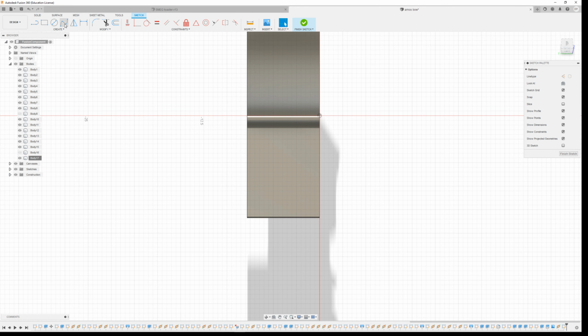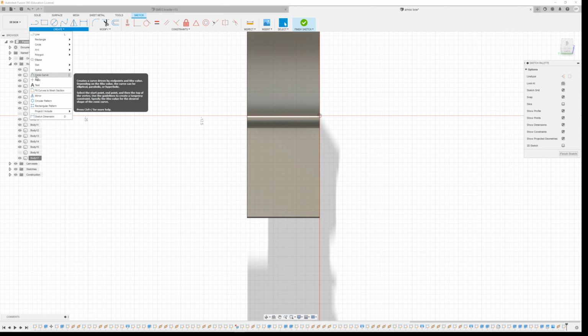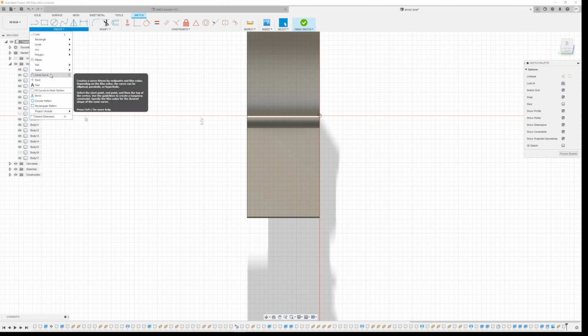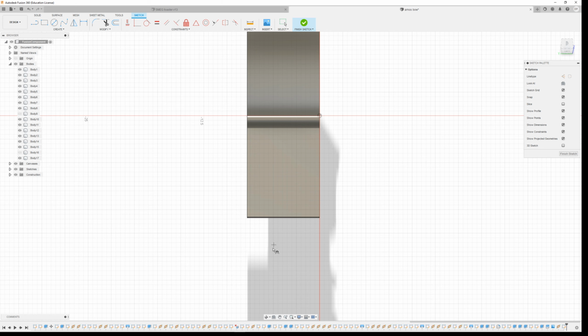And in this sketch, I want to make a curve. I'm going to just play around with the conic curve. Don't know why, just sounds good. Go over here. We want the curve to go from up here to this point to... Okay, that's not how conic curves work. How do conic curves work? I do a start and end point and then the top. Okay, so the start will be here. The end point will be over here, and the top of the curve will be there.